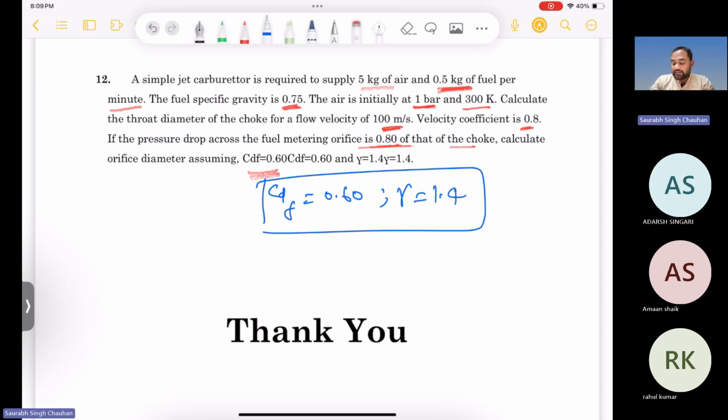See, technically, hybrid means a combustion engine and an electric motor. The electric motor will run with the battery and the engine can run on any fuel. That engine can be a diesel engine, a petrol engine, or any combustion engine. Hybrid vehicles are also of many types. In some hybrid vehicles, you need to charge your battery from some external source, like the electric vehicles. And in some hybrid vehicles, your battery is charged from the engine. It takes power from the engine and gets charged.